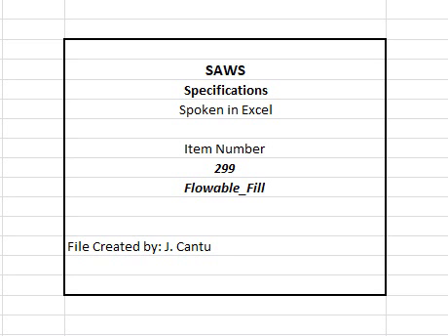Sources not on the HCQMP or other sources to be used in combination with an approved source will require approval before use. 2. Fly ash. Furnish fly ash conforming to TxDOT DMS 4610, fly ash. 3. Chemical admixtures. Furnish chemical admixtures conforming to TxDOT DMS 4640, chemical admixtures for concrete.